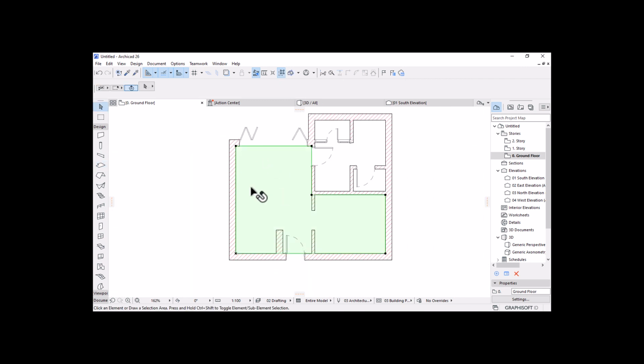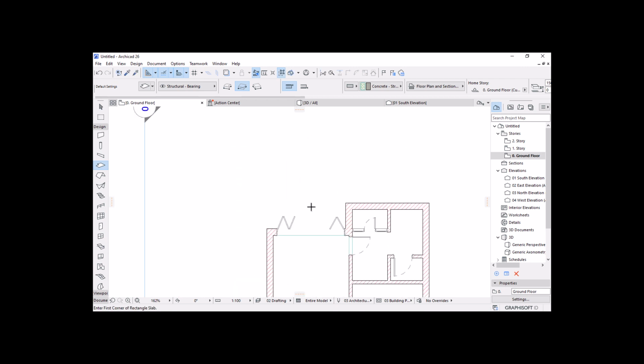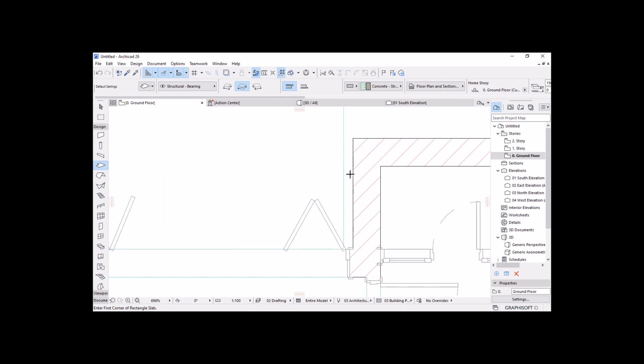So we have placed a slab there, and we need to place another slab for this insert. To avoid going back through those settings, we can pick the parameters of that, and this time I'm going to change the geometry method to rectangular because this is a box. I'll pick this corner and draw diagonally, then pick another corner to place that. We have another one there, where we are starting from this corner, and this side is going to be around 3.6. I'll key in 3.6 by 2.1 is fine. Okay, clearly you could see 3.6 is not working well.